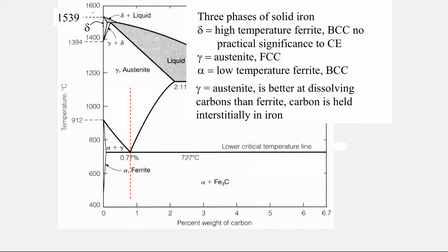It can actually hold carbon interstitially at over 2% carbon, and so we can heat back up steel and have that carbon move into the austenite, and then depending on how quickly we cool the steel, the carbon can or cannot quickly leave and disperse, and we can actually change our crystal structure. And we're going to learn a lot more about that when we get into heat treatments.